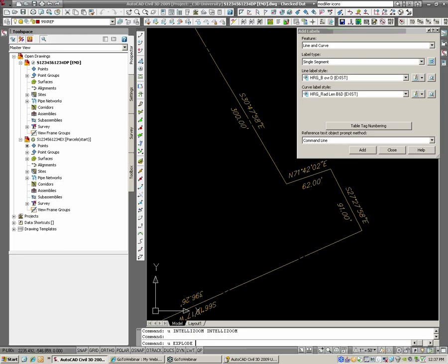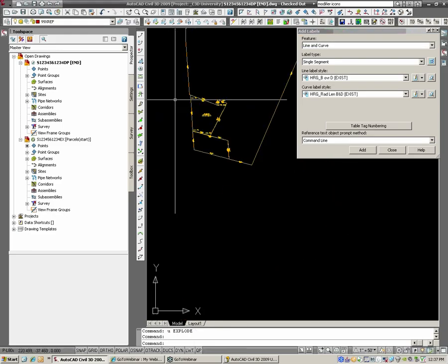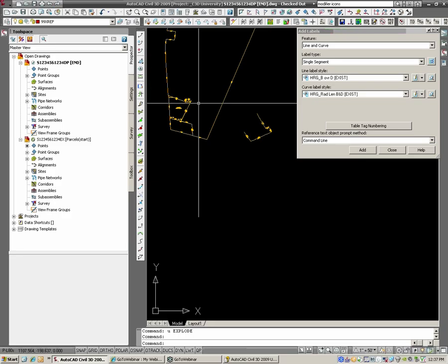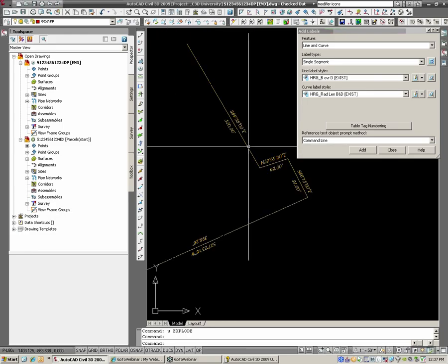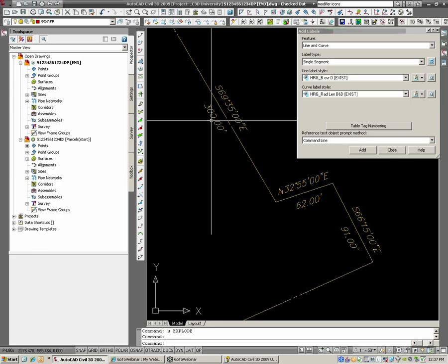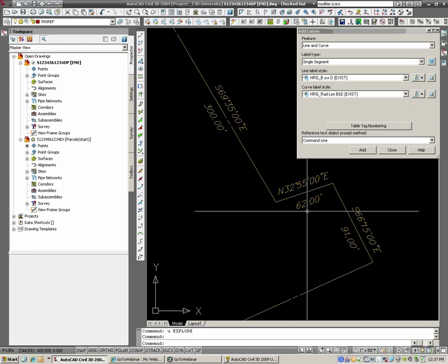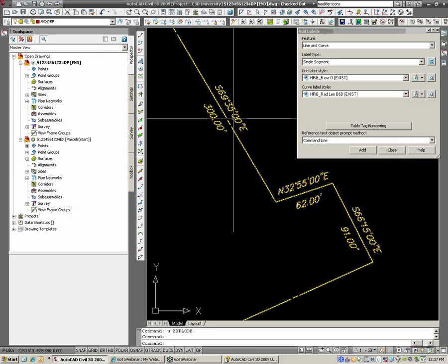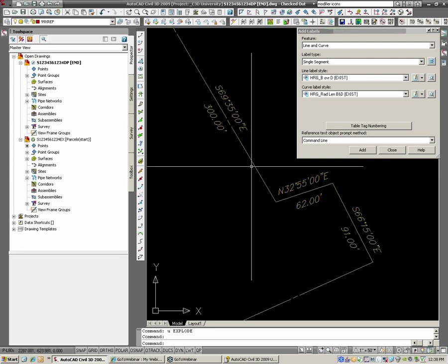But again, in our deed mosaics, in our boundary determination, we're just fitting the pieces together and then they come up with a final determination. So that would be our doing deed plots. Are there any questions on that? It's pretty much straightforward and the same way it's been in Land Desktop, except the only difference is you have to keep in mind if you rotate this deed and then explode it, these bearings and distances are going to change to the actual bearing of this line in the CAD file.